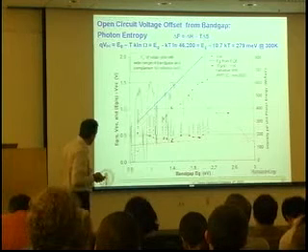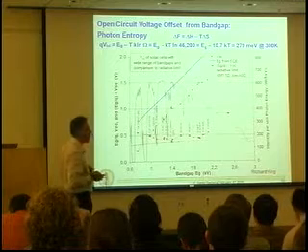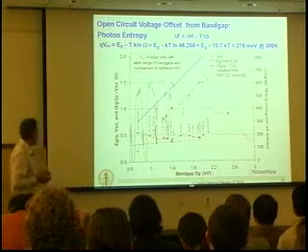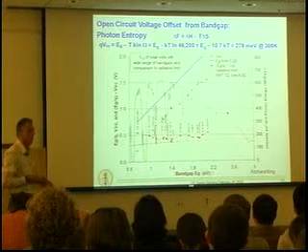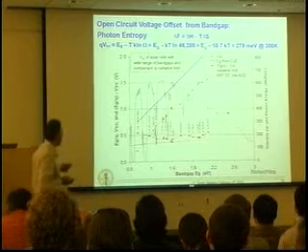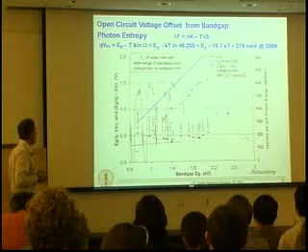And by the way, one of the things that dictates is that it doesn't make sense to make solar cells whose band gaps are substantially below about 0.8 eV or so, because the extractable open circuit voltage is way down here, just a couple hundred millivolts. So fundamentals really end up determining a lot of the operational conditions of even the most ideal materials.